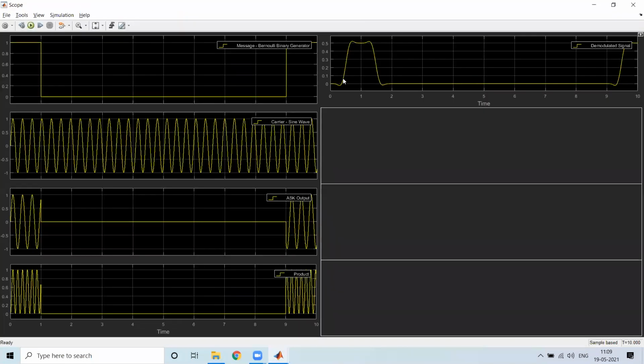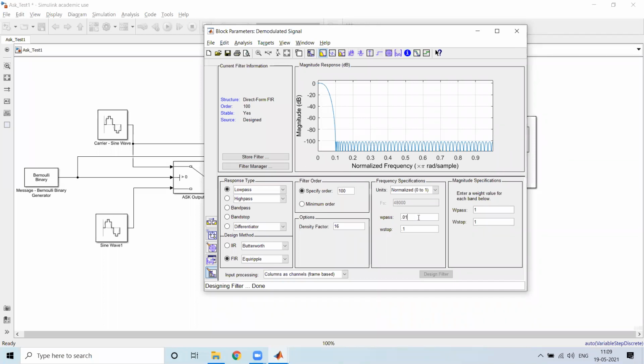Okay, I'm able to get back the information, but what is happening is there will be a slight shift. So the dispersion is happening. You are able to get back this information. If you try to measure the energy content in a given time period, and it happens to be above some threshold value, then it will be indicated as logic 1, and if it is below some threshold value, it will be indicated as logic 0. And suppose there is some error in the detection, then I can go ahead with the information theory coding aspect, wherein I try to see whether I'll be able to detect the error, and if possible, correct the error. In order to do that, you have to apply your information theory coding aspect. So you alter the filter design parameters and try to obtain some results.